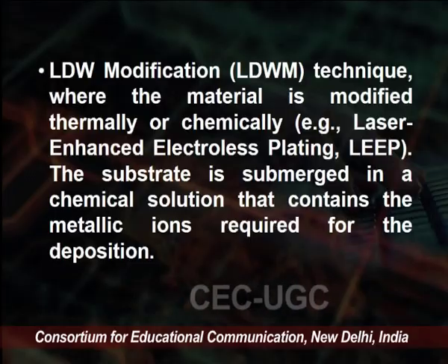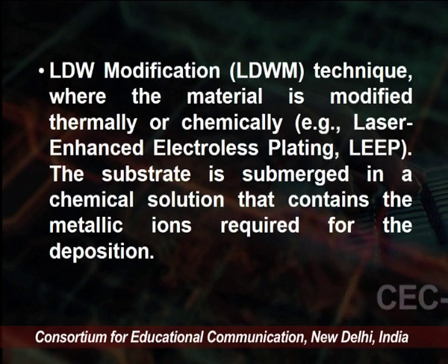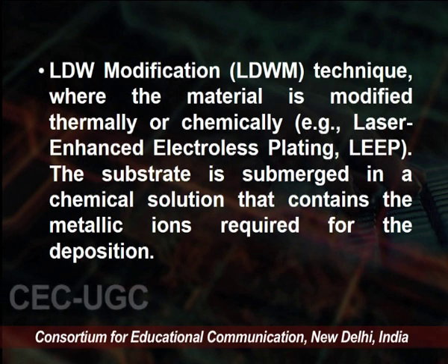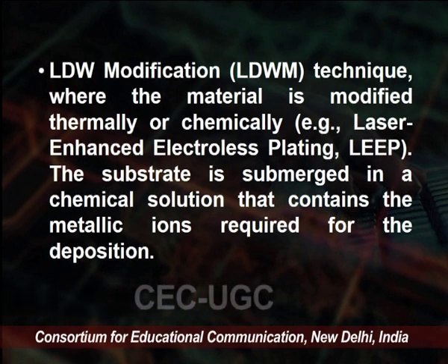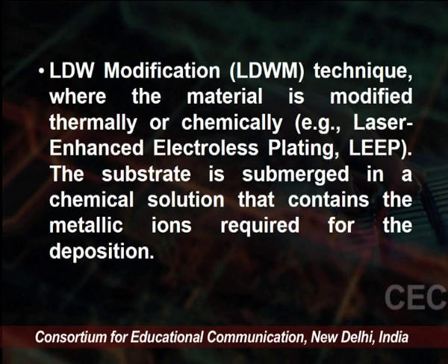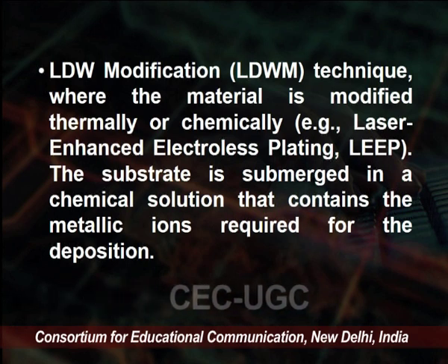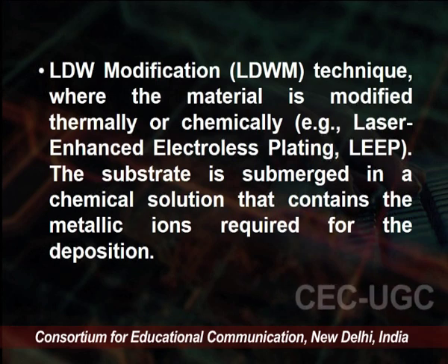The third technique is the LDW modification technique, where the material is modified thermally or chemically. Laser enhanced electroless plating is used. So the substrate is submerged in a chemical solution that contains the metallic ions required for the deposition.